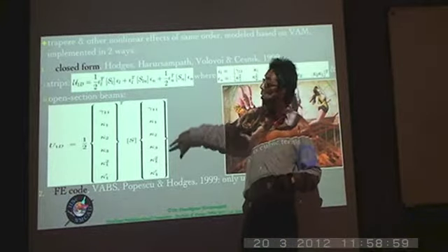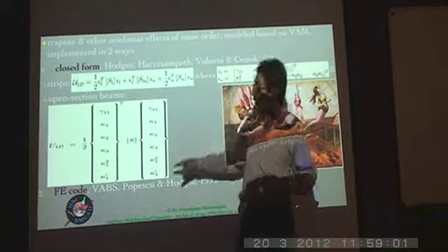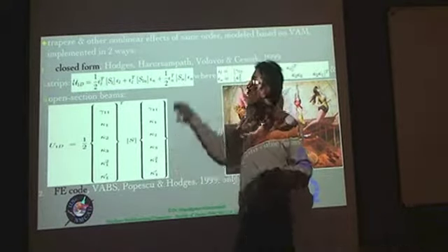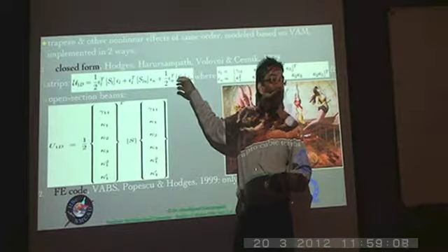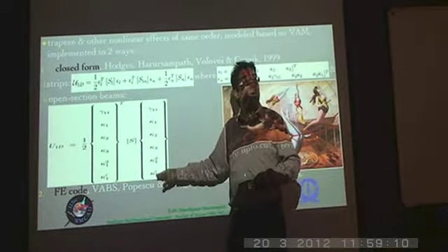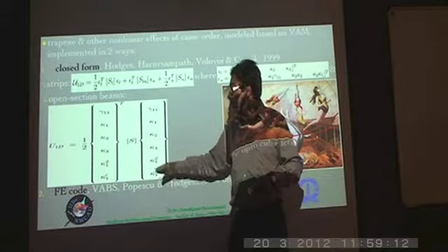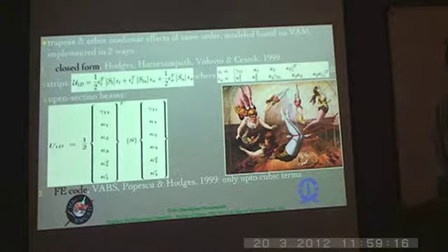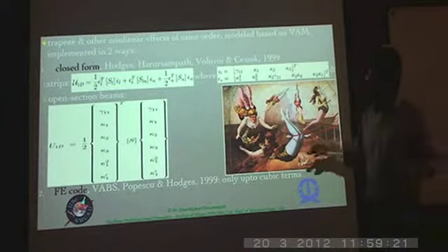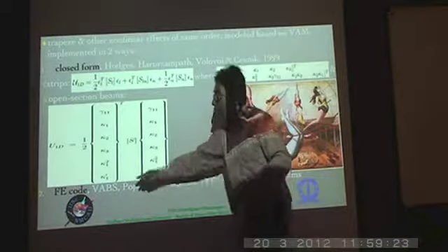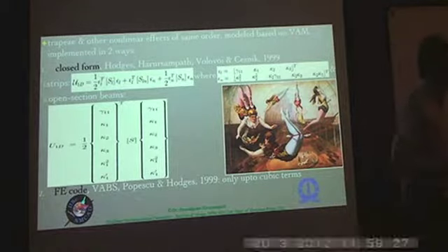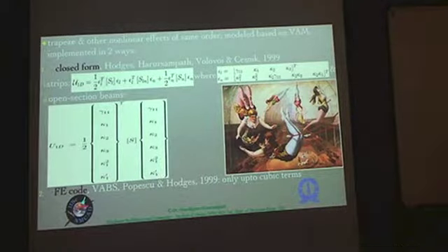But there is a complication here which is not present here, that is in terms of the restrained warping effect. That restrained warping effect is not important at the first order approximation in a strip, whereas it is important in an open cross section, as you see here. This is as far as closed form analytical solutions to nonlinear cross-sectional analysis is concerned. Now let's, in the next slide, focus on how the same thing is handled by the code VAPs in terms of a finite element kind of an implementation.